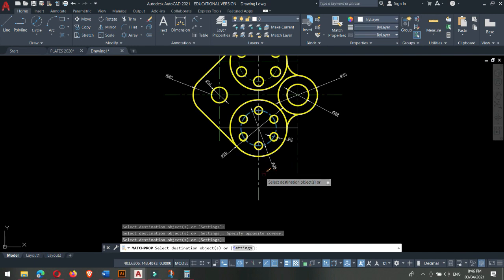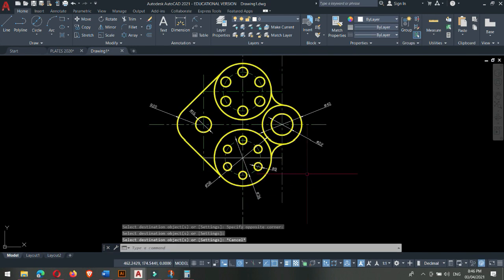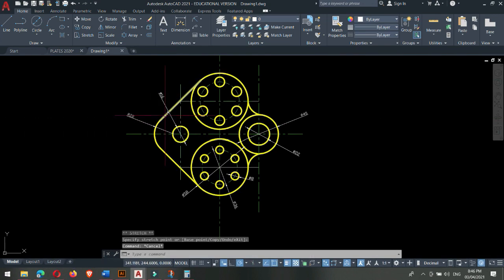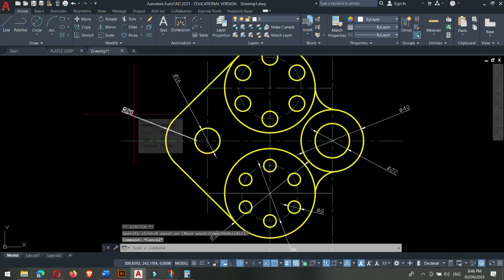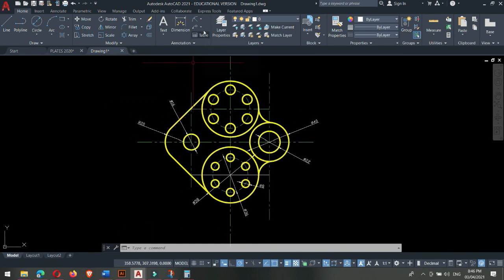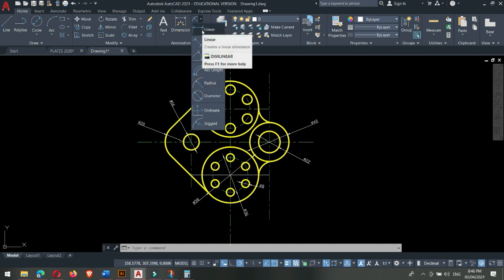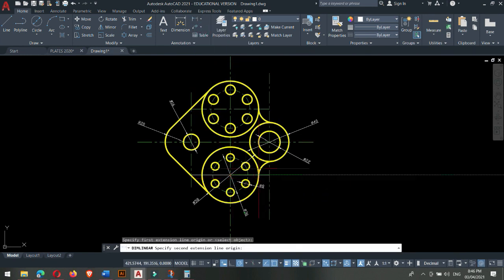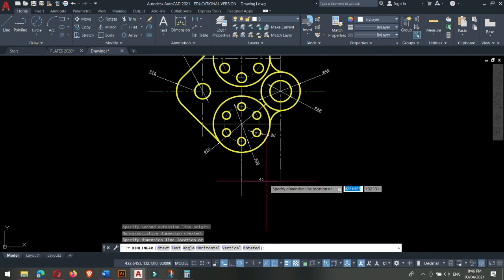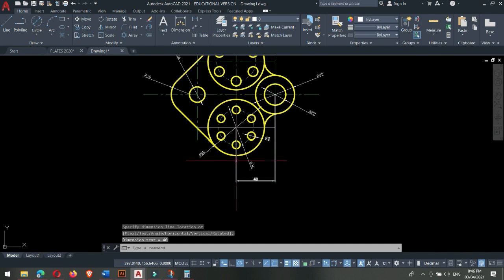And we're good. Alright, so what's the next step? The next step is actually to make sure that the dimensions are accurate. So we have created a radius and a diameter. This time we're going to use a linear dimension. Linear means straight. So I'm going to left click here and identify center point to center point. If you can see, it is 40. Enter.